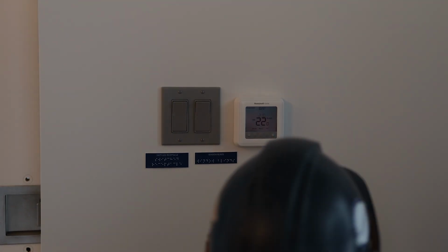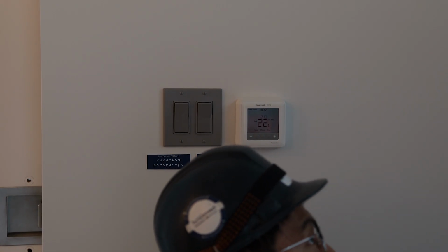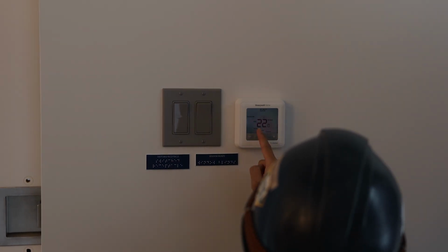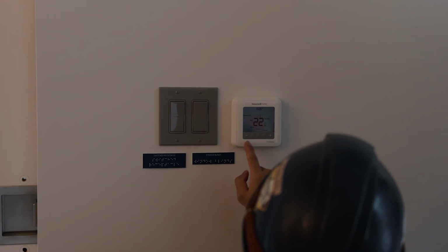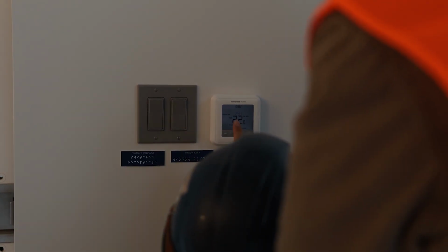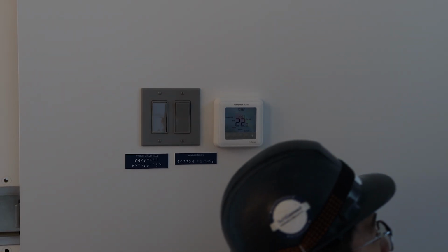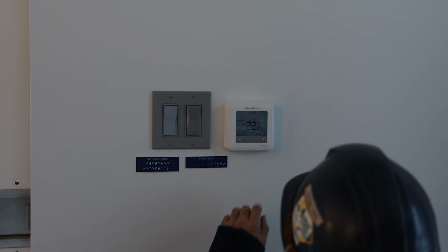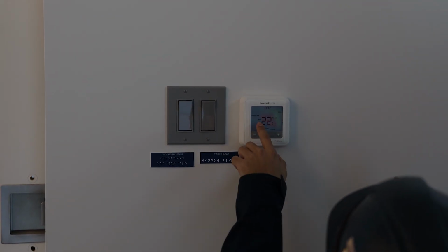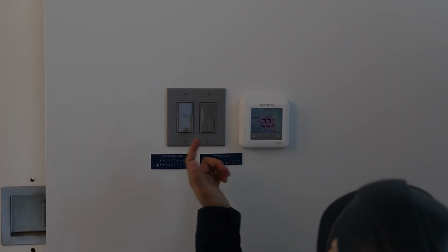And to answer your question, there is a temporary hold or permanent hold for the set point. Once you adjust the set point, let's see if I increase it to 23, here it's a temporary hold, right? And you press this button, it tells you permanent hold. So this set point is going to stay there permanently, not temporarily. It's 4 hours. If they want to lower to 21, here it's at permanent hold. Right now it's already in permanent hold mode, so we only need to adjust the set point, and it's already permanent hold automatically.